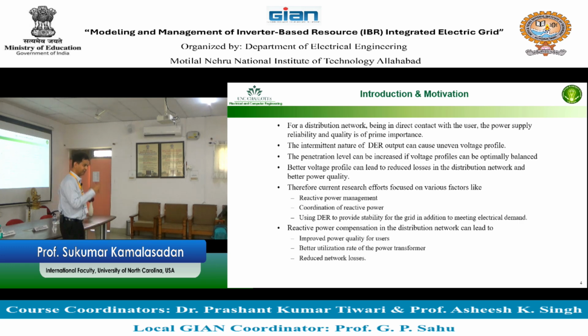with a few devices with respect to the number, but reactive power coordination is difficult with respect to time. For example, some are pushing reactive power faster, some are pushing reactive power slower. You have to maintain the time difference, or time scale separation. So coordination is mainly related to time, not to location, because 3 or 4 devices can be controlled. So that's something you need to follow. Yes? No?